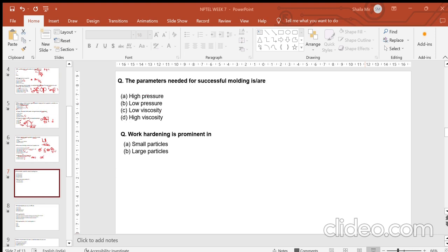Even if it is for liquids. For example, here it was a weighted average of a material which is a powder, a solid material. But if you have two liquids and you are mixing them, and you want to find the density of the liquid that is formed after mixing the two, we can also find the density using the same rule. So this is a very general rule for mixing. If you are mixing two or three species, you can use this formula in any way possible. You are multiplying the weight and density to find the theoretical density, right?